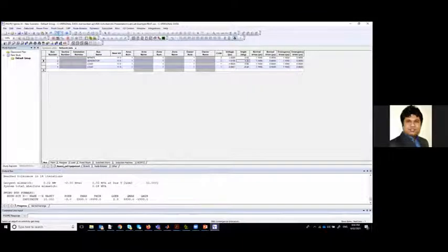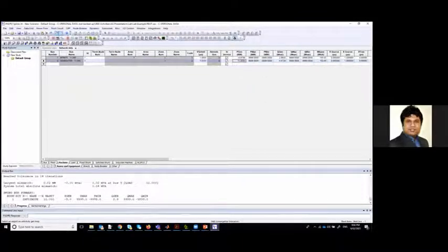Now let's go to the machine tab. We put 15 megawatt for the generator, and it's still 15 megawatt. We didn't put any reactive power, and we got reactive power here. For the infinite bus, we did not put P and Q, but we got P and Q here. Though it is negative, because as I told you, the infinite bus is an infinite source. It can consume or deliver power depending on the system requirement.